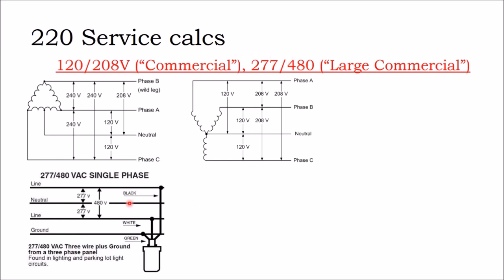All right, so there's a 120-208 electric service, and 277-480 is another common electric service. And so what we might have is point to point in 3 different phases, and the phases, instead of being just complete equal opposites of each other. When you get into commercial design, the kinds of transformers, you get a little custom fit to purpose.